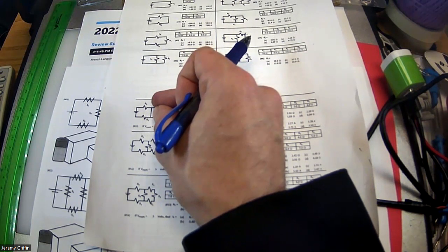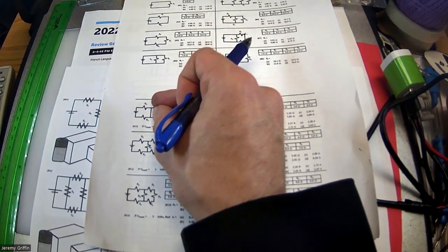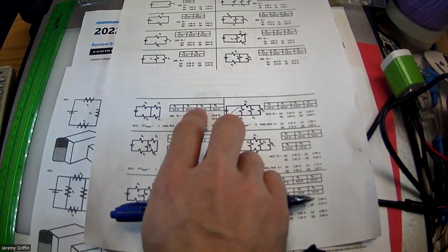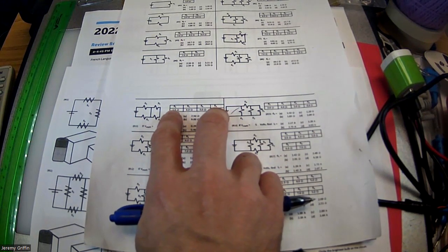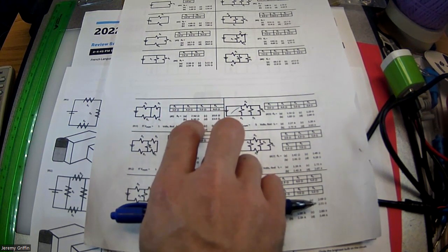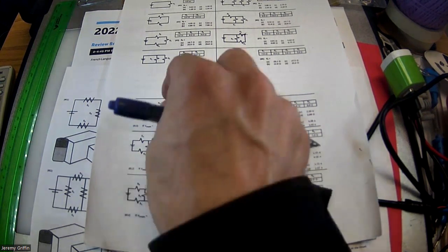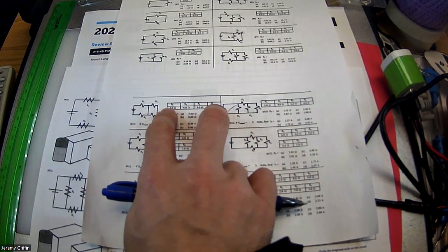Your entire circuit for number 9 is just R1 and R4 in what, series or parallel? Series, yeah, because it's just sequential, one after another. So for number 9, you completely ignore R2 and R3. They're not even part of the circuit. Just go straight to R1 and R4 and add those together. For me, I have 3 ohms and 6 ohms, which gives me 9 ohms. Did everybody do that on your paper? On number 9, find R1 and R4, the only ones on the circuit. They're in series with each other, so just add them up.